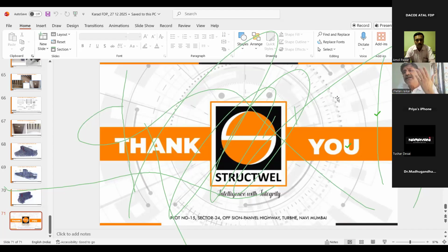Most technocrats are unable to identify the root cause of a cracking in a heritage building. If the root cause is settlement, the challenge is at the foundation level, and you start grouting, it's not going to help. You start stitching, it's not going to help. You start using helifix bars, it's not going to help. You have to arrest the settlement first. Now, the challenge is arresting the settlement. In many cases, there is a road abutting, so the corporation does not allow you to excavate.